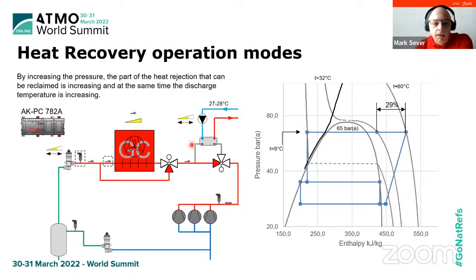What you can observe here is that now this high pressure valve starts to operate more. I mean, it starts to tune this pressure in the gas cooler, but also your pump on the heat recovery side is also tuning to get heat out of the CO2 system. The fans very likely will be close to their maximum operation because we are trying to reach this temperature out of the gas cooler on a low level.